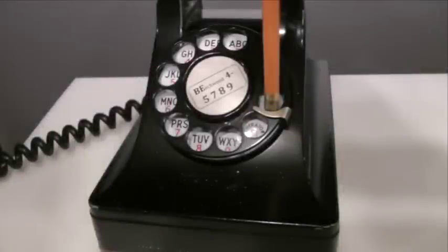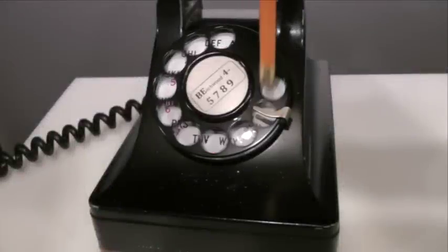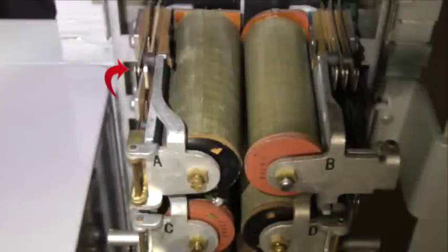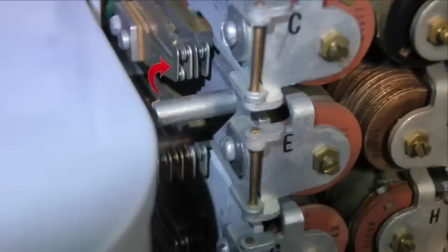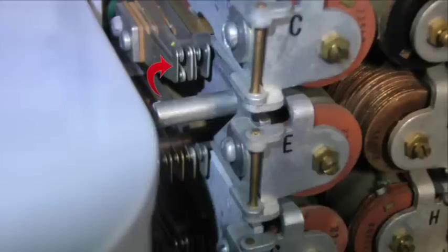When the dial starts to return, the loop opens at the beginning of the first pulse. This releases the A relay. With only the B relay and the VON springs operated, the path for operating the E relay is now closed. The E relay monitors the units digit pulses, and when pulsing is finished, it transfers the switch operation from rotary stepping to the ringing stage. It is a slow release relay and remains operated throughout the units digit pulsing and permits time for a called line busy test to be performed.